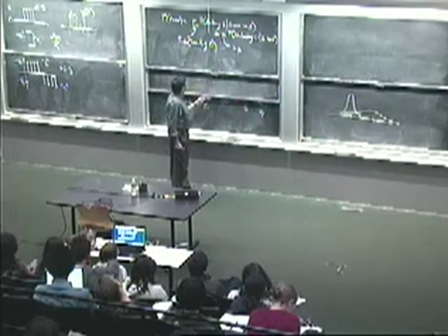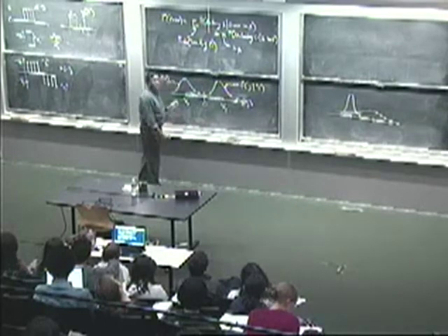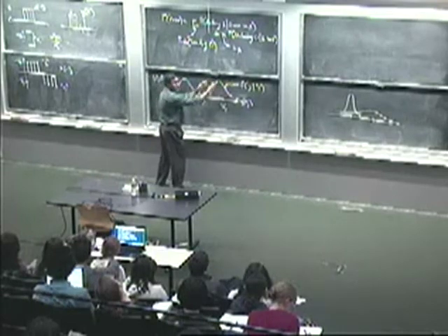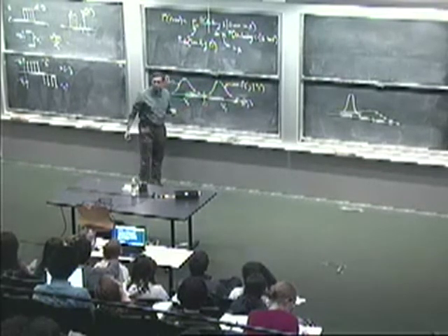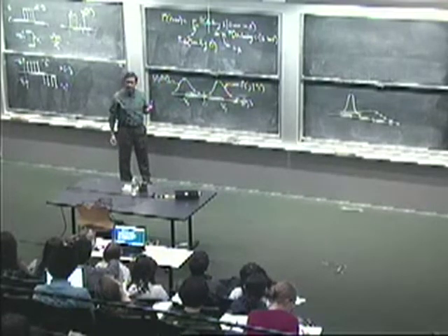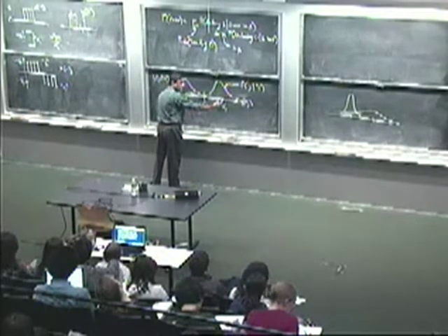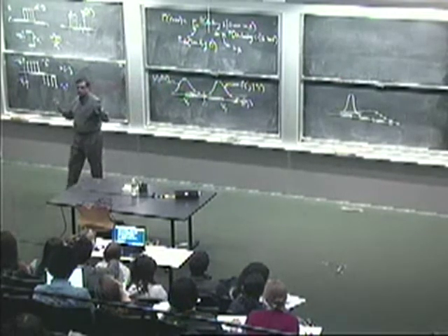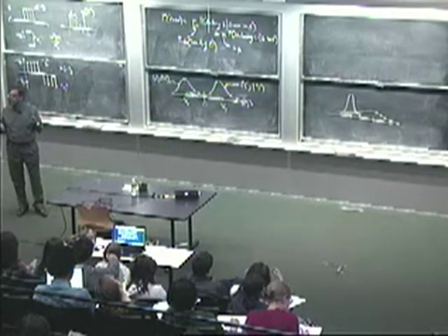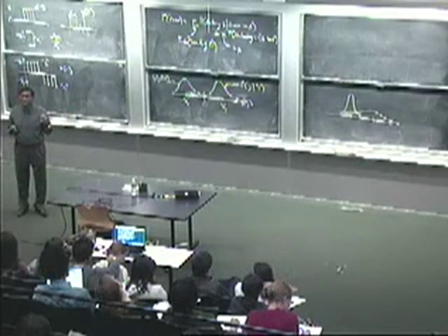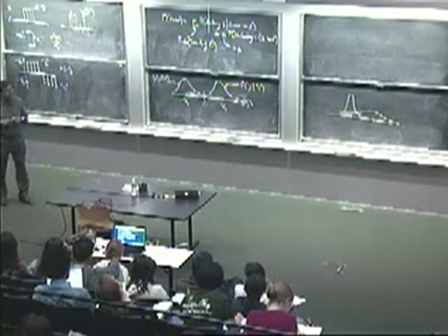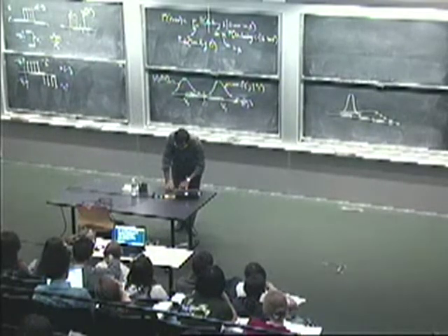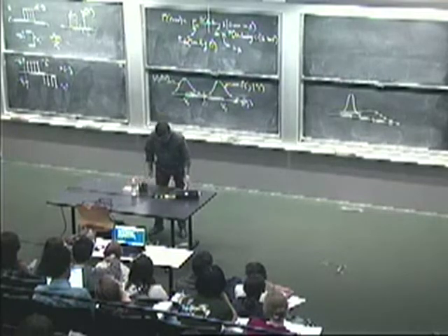Okay. Visually, what's going on? Let's go back to this picture. When the noise decreases relative to the signal, what's happening is that these Gaussians are getting more peaked, and they're pulling in more tightly. And so there's less chance of confusing the two cases. Okay, so it's as simple as that. It's the separation between these two levels divided by the standard deviation of the noise that's really going to determine performance. How far apart are these two cases relative to the standard deviation of the noise? That's the square root of the signal-to-noise ratio. Okay, and that's what determines the probability of error in this case. Okay. So are we done, or could we be doing better?